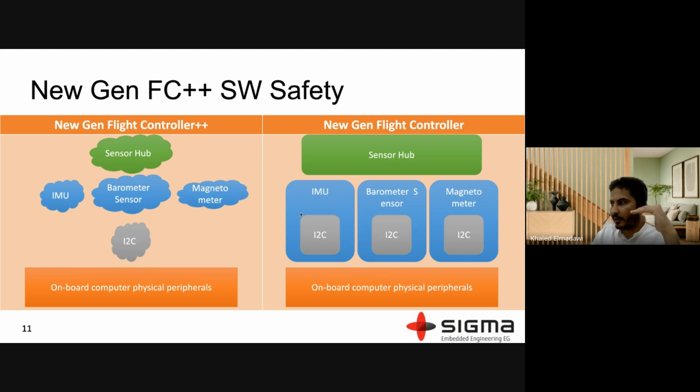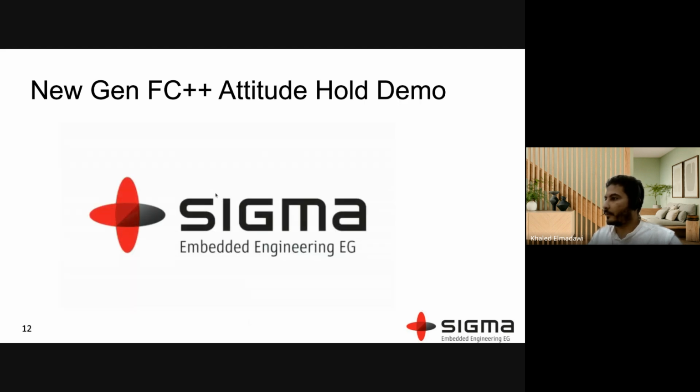For example, if you have the IMU by itself, it will work out fine at 1K with this setup. Then if you add more sensors to it, it will drop from 1000 to 800, and then to 100, and it will just keep dropping. Why is that? This might be one of the reasons: the conflict of fighting over different resources. That's briefly our software stack.